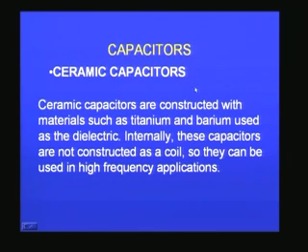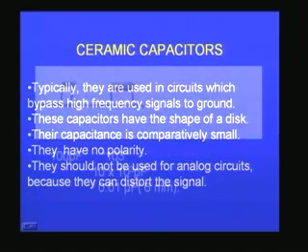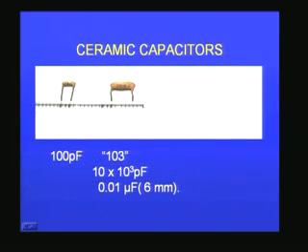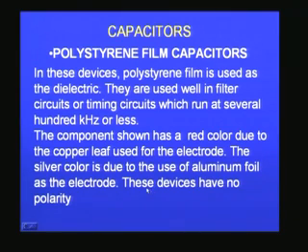Then you have another type, which is called ceramic capacitors, and they have barium titanium oxide, which is used as a dielectric internally, and they are used usually for high frequency applications. Then you also have, these are some of the ceramic capacitors. One is 1000 picofarad, and the symbol they use, for example, you can see here, I hope, is 103, which corresponds to 10, the first two digits, times 10 to the power 3 picofarads, which is equivalent to 0.01 microfarad.